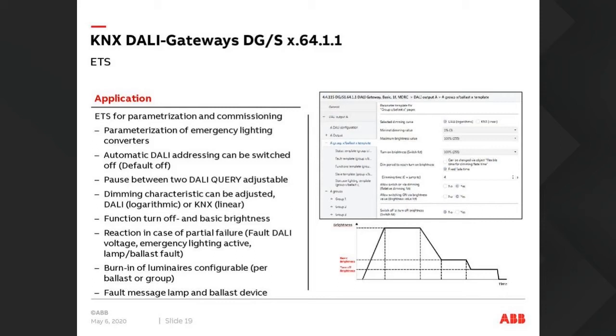We can also query the lamps and the ballasts. We can find out what information it has. We can switch automatic DALI addressing on and off. Generally, I'd say switch it off and handle that manually yourself. It's probably quicker to do it.